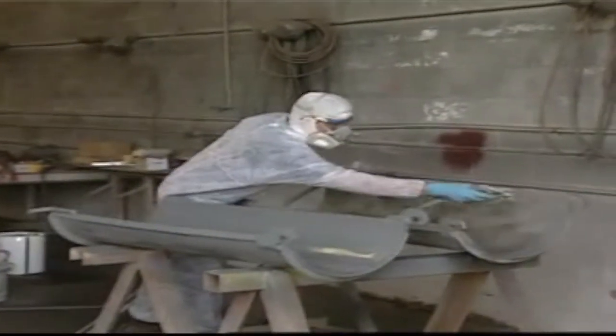We at Graco have identified 10 factors that have a crucial effect on transfer efficiency. They are: operator spray technique, fluid delivery rate, atomizing air pressure, target size, type of application tool, condition of the application tool, configuration of the target, air velocity in the spray booth, fluid pressure, distance of the spray gun from the target.